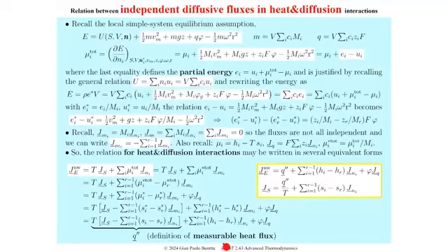So the bottom line is highlighted here: we have finally written the fluxes of energy and entropy, which are needed to make the energy and entropy balances, in terms of the flux of heat transfer, the measurable heat flux, the fluxes of constituents, but not all of them, only up to r minus 1, and the diffusive flux of electrical charge. So this is basic to analyze any of those cross effects that we need to do.